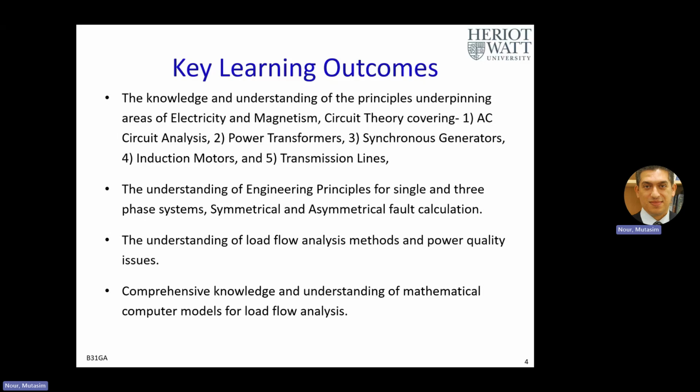Then an understanding of engineering principles for single and three-phase systems, including symmetrical and asymmetrical fault calculation. If a fault is going to happen across our transmission or electrical power system, how do we calculate the fault? Normally we need to know what the fault is in order to protect our system. How do we protect it? By circuit breakers, switchgear, fuses, and so on. So we'd like to find out the fault level, how much current flows when we have a fault, in order to include a circuit breaker in between.